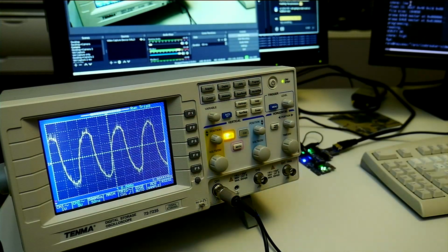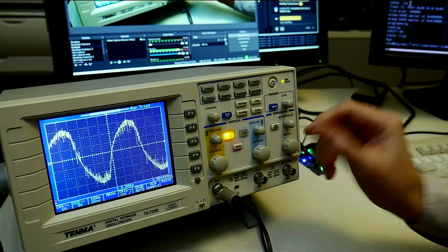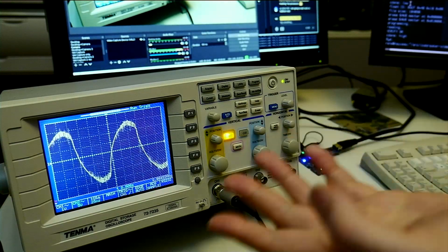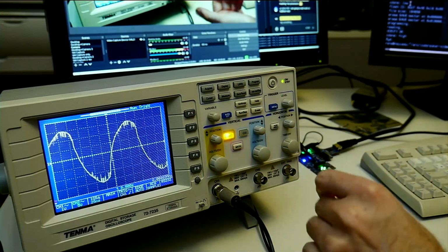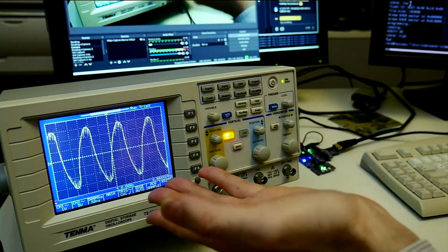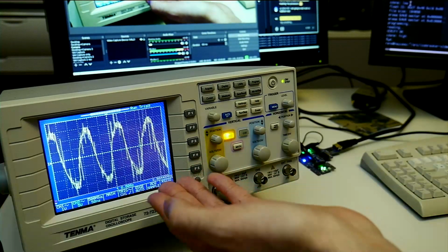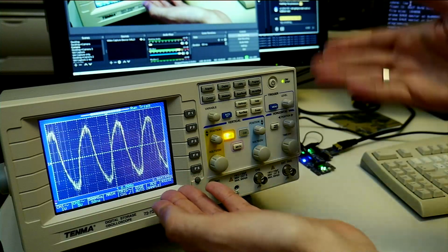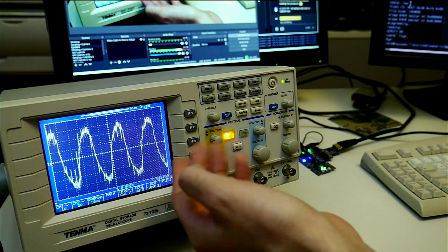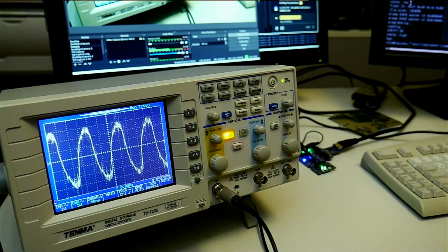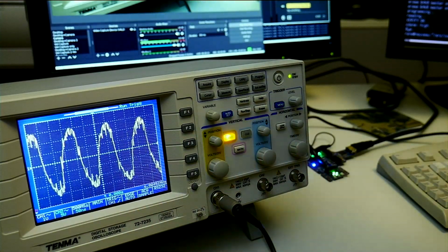This is a signal, and to some of you it might already be surprising that this is not super amazingly rectangular. This is just the output. If you look at some kind of clock on such systems, that's not fully square, obviously. And we are basically incrementing, so we increment this and output the last bit. So right now this is counting with 12 megahertz, and the digital scope here correctly measures this for us as a relatively precise 6 megahertz.